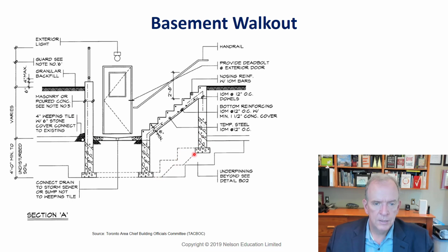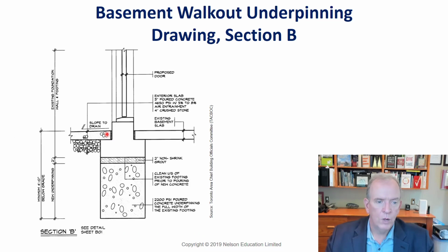And the reason this is stepping down is because you've got to maintain that 4 feet below grade. And then, of course, this is deeper. So we've got to ensure that at no point are we less than 4 feet. Because if we are, then the frost can just get underneath this and heave this. Because at this point here, this is wide open. So the frost would go right through down here. If we only went 4 feet down from there, say we went to there, well, the frost would get right underneath there and start heaving everything. So we have to protect it that way.